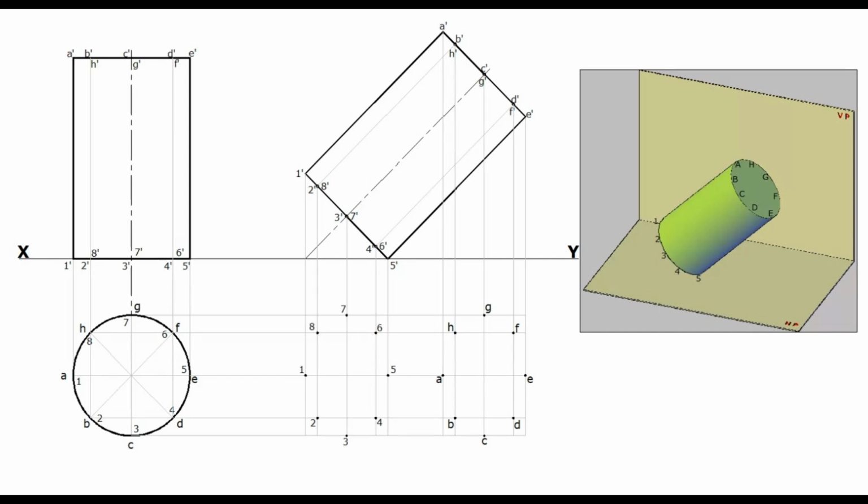The circular bases can be seen as an ellipse in the second stage plan. The top base is fully visible, hence should be drawn as dark. For the bottom base, only the outer half will be visible. Hence, only the outer half of the elliptical shape should be dark. The inner half will be invisible, hence should be drawn as a dotted line.